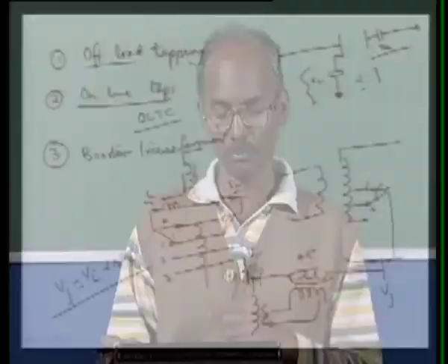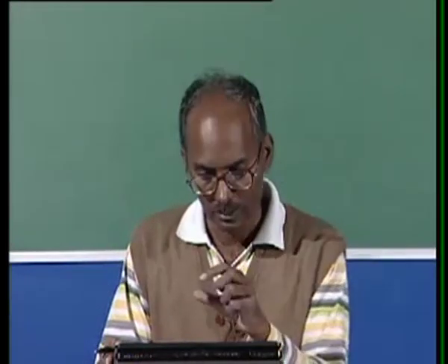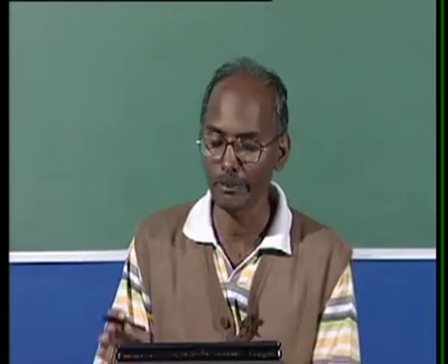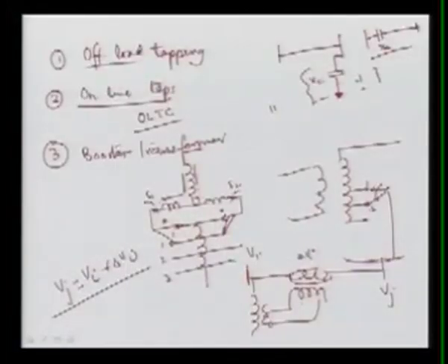Again, the purposes of these two connections are different. Normally, if you are connecting the shunt, the purpose is to improve the power factor, or to inject reactive power, and to improve the voltage profile of the system. If the voltage of this system is changed, there is a possibility that the voltages of neighboring connections will also be affected and modified. So what we are doing is meeting the reactive power requirement locally. Let's suppose a load is connected here and it has a poor power factor, so the reactive power will be provided here.